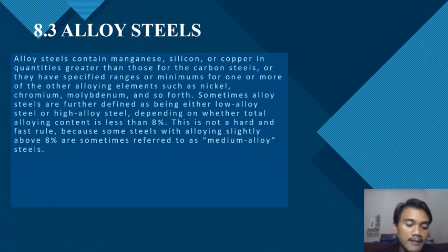The low alloy steels constitute a category of ferrous materials that exhibit mechanical properties superior to plain carbon steel, resulting from the additions of such alloying elements as nickel, chromium, and molybdenum. High alloy steels with alloying greater than 9% are typically classified as high alloy steel. And stainless steels are the major types of high alloy steel, but two other types are ultra high strength nickel cobalt steel and maraging steel.